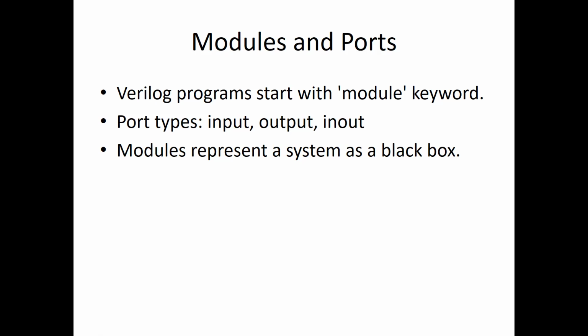So everything in Verilog starts with the keyword module. Module is the keyword where we will start writing a program. Suppose we are writing a program for an AND gate. Then we will start defining the code with the module keyword, that is, module and AND gate, or any name we can give. But for proper identification of a particular circuit, and for easier explanation, we will write a particular name by using the keyword module.